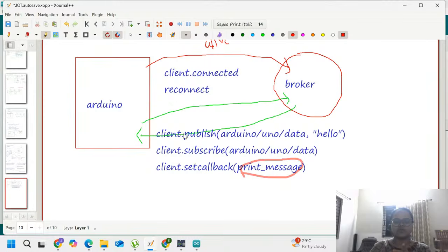I am publishing hello from the Arduino to the broker. And what topic? Arduino UNO data. So what will happen on the Arduino? I'm subscribing to the same topic, so I should get hello back.